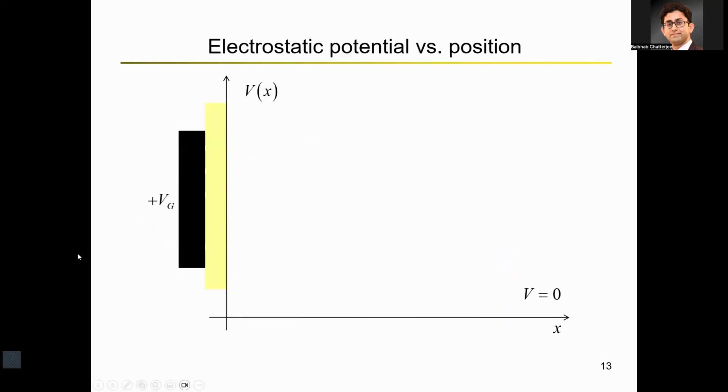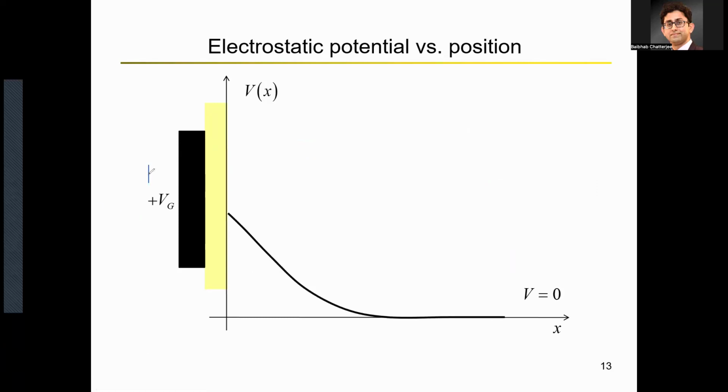If you plot the voltage from the left side to the right side, you'll see that because you are applying a plus V voltage at the metal gate, you have some kind of oxide insulating layer, and right below it you're creating a capacitor structure, a metal oxide semiconductor based capacitor. Metal is conductive, oxide is an insulator, semiconductor is somewhat conductive. So you're creating not a perfect capacitor, but somewhat of a capacitor. If you have plus Q charge on one plate of the capacitor, the other plate will hold minus Q, and that's how you analyze capacitor based structures.